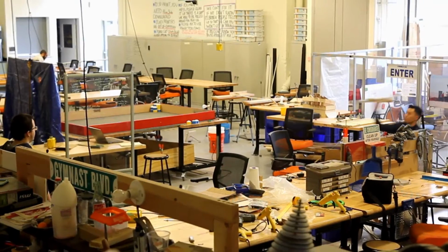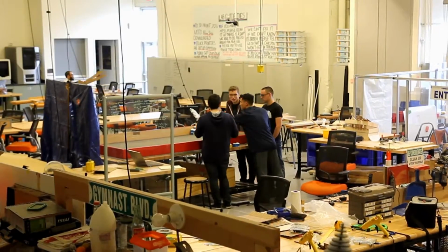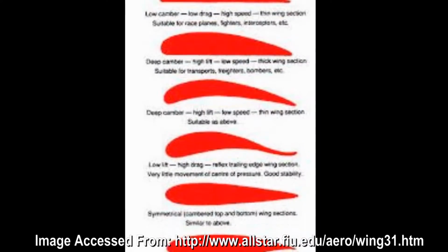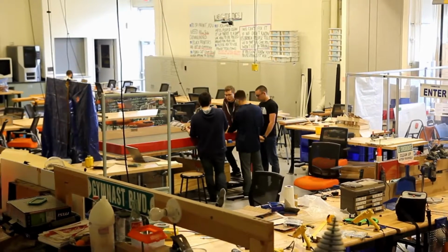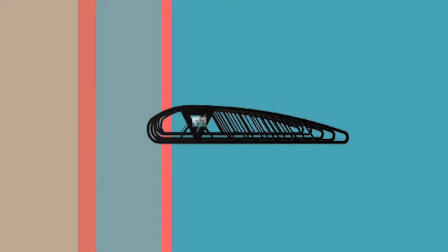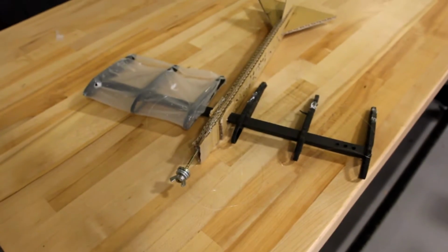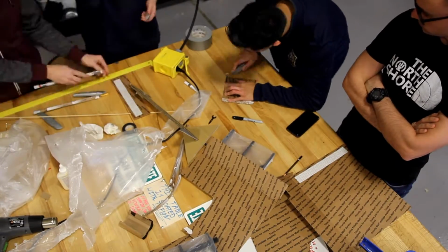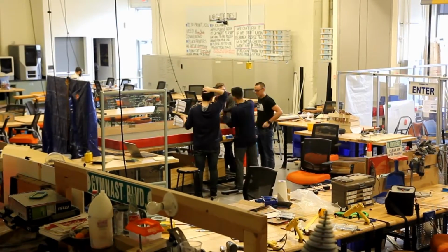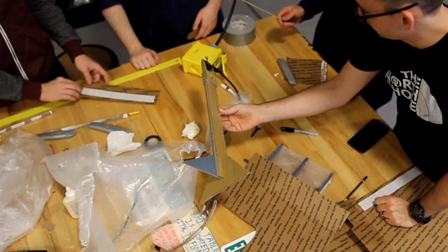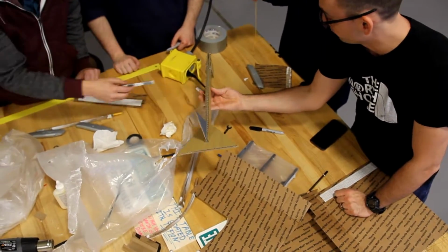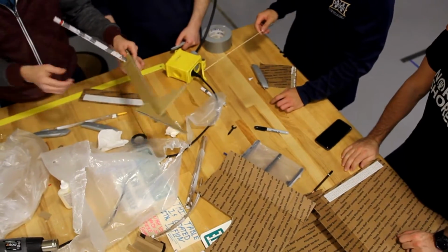While conducting research on the most desirable airfoil shape, the team concluded that a deep camber rib would provide ample lift while not compromising on stability. It was also important that the shape could be repeatedly produced. The first attempts of this design were made using the 3D printed Nylon X. Our initial impression of the 3D printed wings was that the infill of each rib had increased the weight quite drastically. We still went ahead and attached these wings to our body and did several test flights.